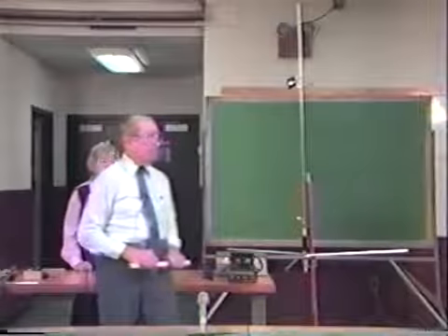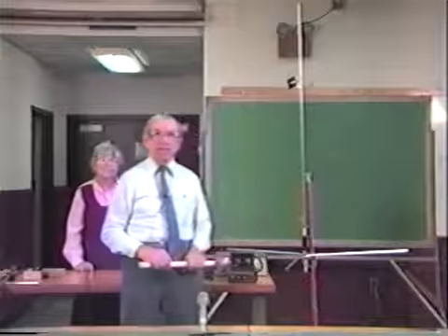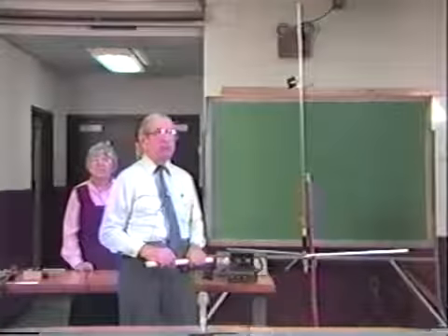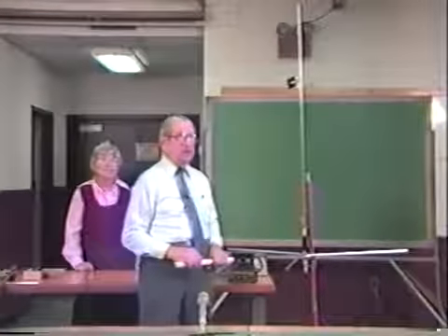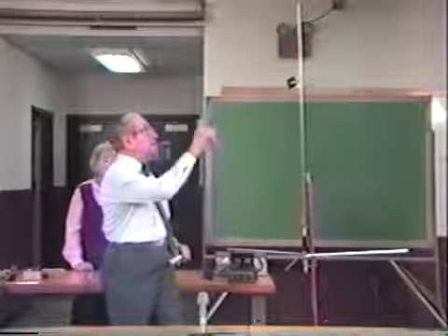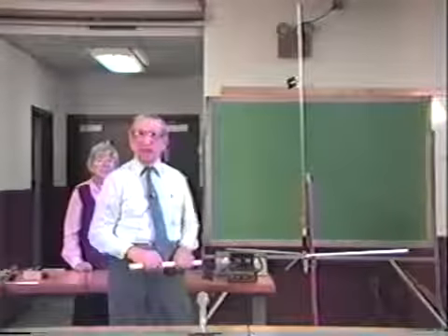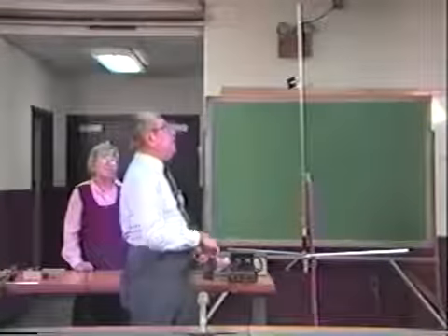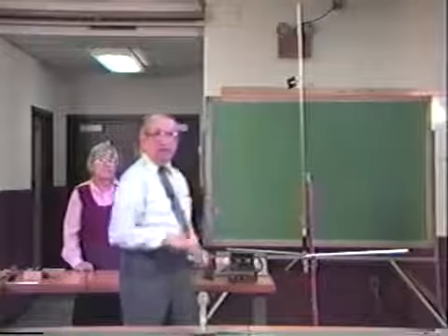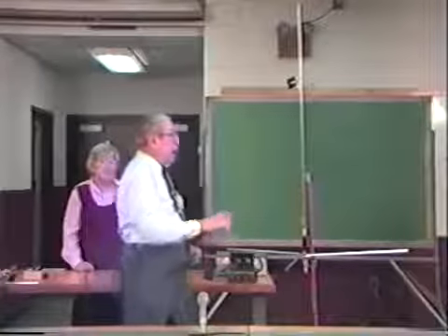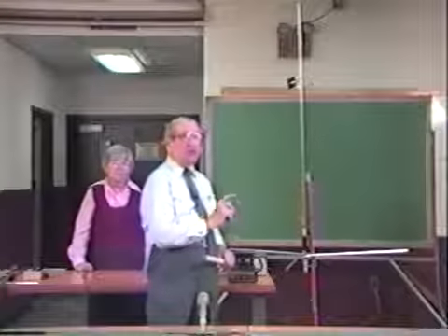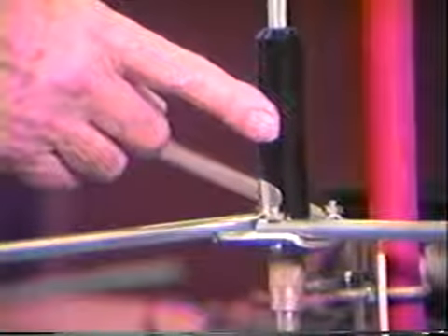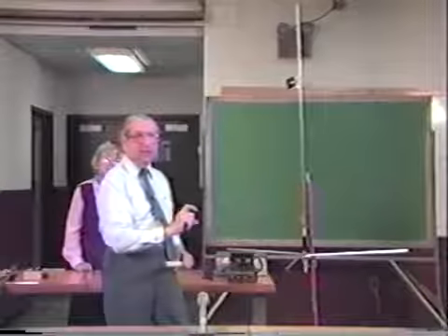We're now going to demonstrate a different type of vertical antenna. It's commonly known as a 5/8 wave vertical antenna, used in mobile installations or in fixed installations as well. You can see the antenna here. You notice it's quite a bit longer than the antenna that we demonstrated before, but it's cut for the same 146 megahertz. What we have here is a 5/8 physical length of the antenna. Now, actually, in reality, this is electrically 3/4 of a wavelength long. But this little coil in this base is picking up 1/8 wave of the resonance to create the resonance, okay?